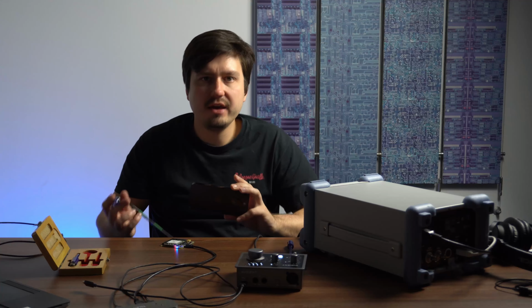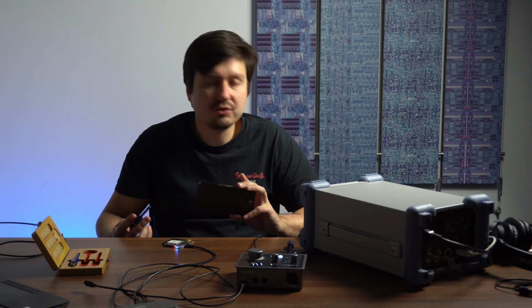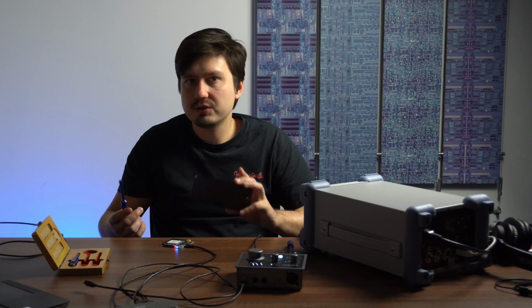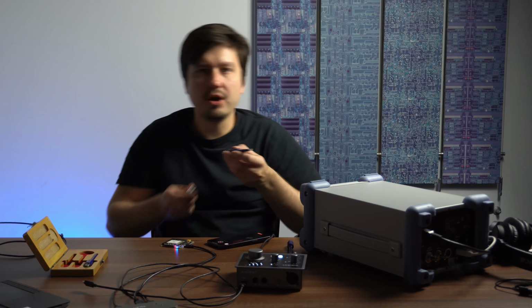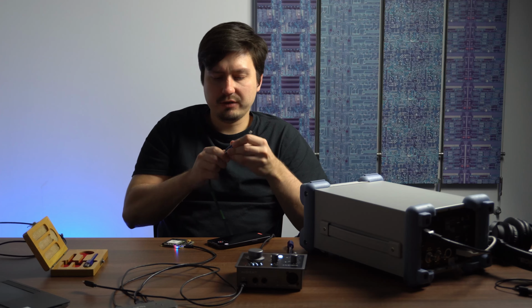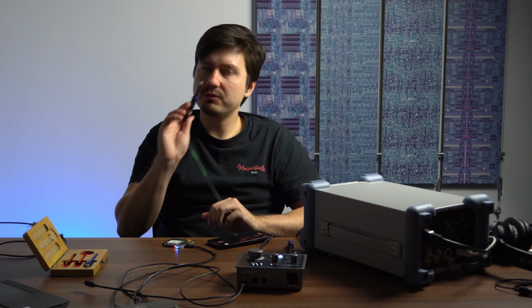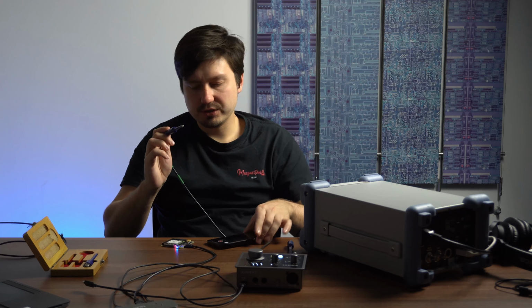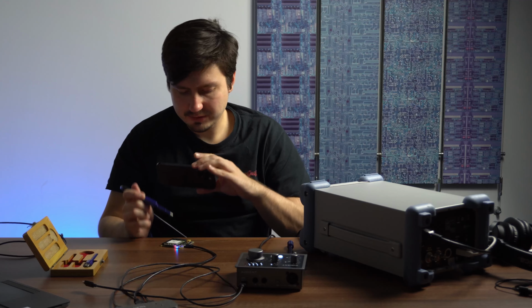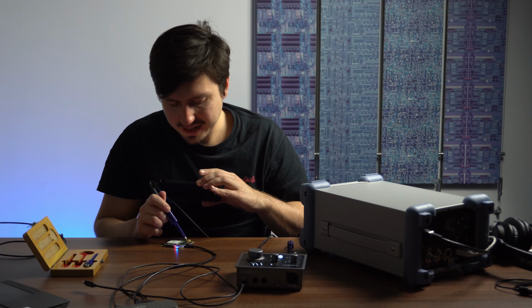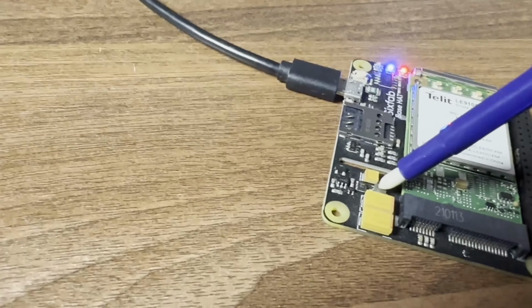But before we do that, let's switch the probe again. So now I use this broadband probe to identify the area that is of interest. And now I'm just going to narrow it down even more. So now I'm going to switch to this near field probe that looks like just a pencil, and it's quite pointy, which is really interesting to see what that's going to look like. So I know exactly where to point it now. So I'm going to go straight for it.